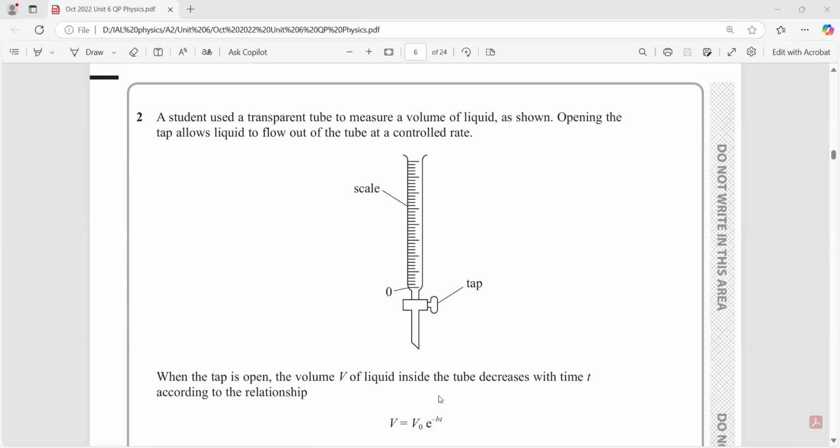Same thing, the marking here, if you see this marking is not starting from the bottom. Like marking starts above the bottom. So it means there is some liquid still coming out, but we don't know how much liquid will move out. So because of that, the scale is not starting at zero. Otherwise, this should be zero, then one, two, three, four. But zero is starting above. So which error is this? Systematic or random? So this is a systematic error.